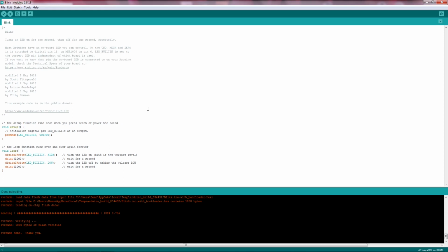Well, say you want to do millis, right? In the Arduino libraries, you want to calculate the millisecond for making of a delay. You have here in the blink, there's a delay that says 1000 milliseconds, right? So the thing has to know what is 1 millisecond, how long it takes. Guess how the thing knows it? Well, when you compile it, you pass a define, it creates a define inside everything, even here you would have it, which called F_CPU, all big case, and it's the number of cycles per second.